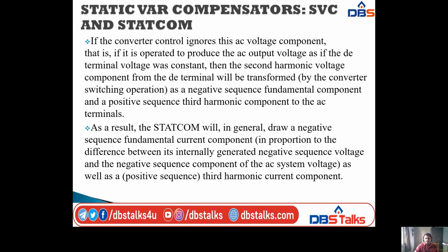As a result, the STATCOM will in general draw a negative sequence fundamental current component, as well as a third harmonic current component.